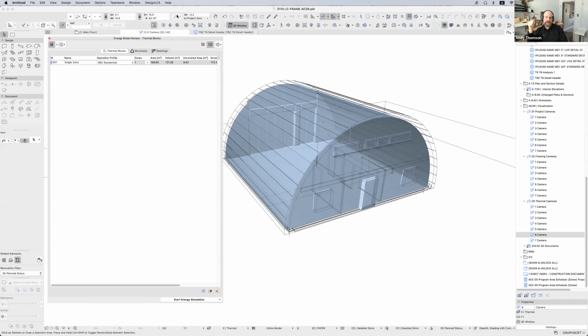By the time they added the U values that we had for our assemblies, the shading, the activity levels that we anticipated, and all the other factors that we had considered for our model design, their model predicted 7 tons of cooling. So we're not doing engineering, but we're using the early stage building energy model to have an intelligent conversation with our sub-consultants about what the predicted loads, I will never use that word again, what our targeted loads were, so that we can work together to optimize and coordinate.